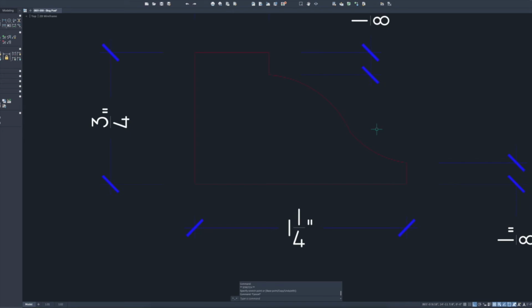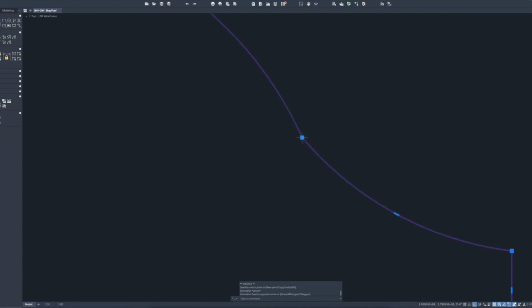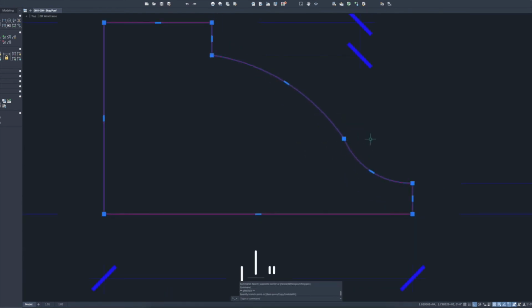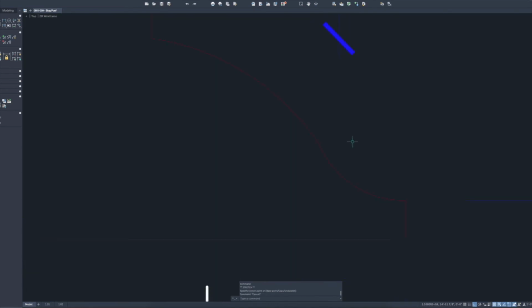When you're working with CNC machines, what you draw is exactly what you get. So let's say you have this instead, and you get this weird hump on the molding. If you were to send this drawing file over to your cutter manufacturer and he were to duplicate this, you would wind up with that little lump on every piece of molding that this custom cutter made.